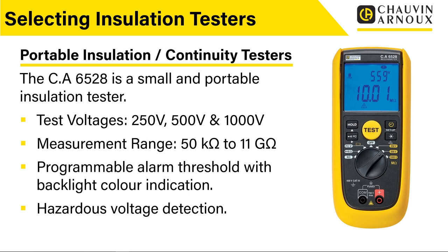So it gives you a nice clear indication. So if you're testing quite a lot of things in one go, you don't want to be just staring at the screen all the while seeing that going up and down. You can actually hear and you can see that alarm function, and it tells you that the insulation has got a problem. It's also quite useful if you're testing a piece of equipment, maybe you're leaving it connected up to the instrument and you're doing some alterations, or you're wiggling some cables or something like that in a piece of equipment, and then you'll get that indication. So the alarm function is quite good on that.